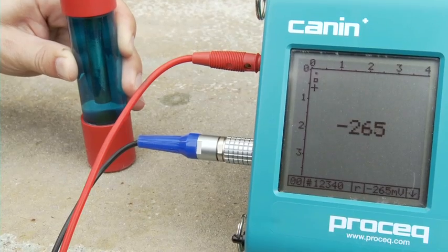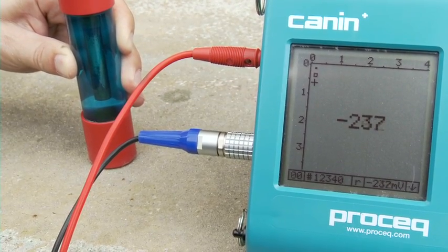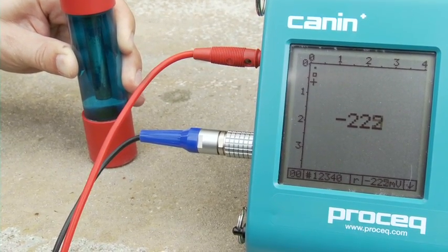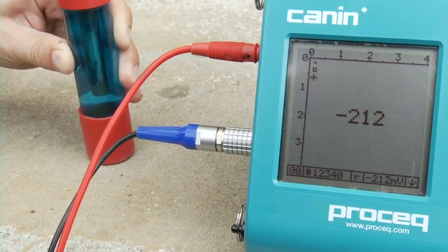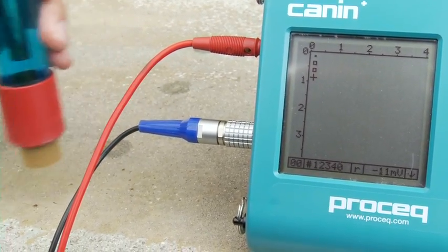Following the measurement, it should be possible to see a wet patch when applied on dry concrete. If this is not the case, then the foam rubber plug should be moistened with water again.